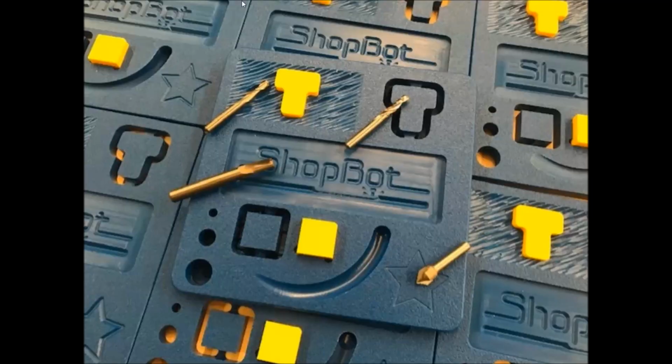And the last thing we should look at is actually cutting this 8x8 plaque out. And the point of this is I want to focus on tabs a little bit so you can make sure that you're adding in tabs to keep that part from moving while you cut it out. A tendency if you forget to do tabs is that part's going to shift while cutting. You could either snap a bit or the material could move into the bit and actually damage the piece of material that it is that you need for your project.